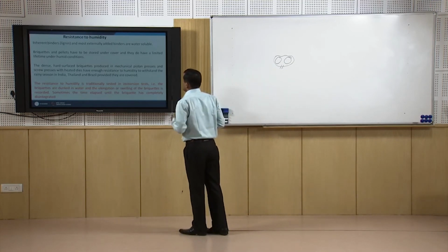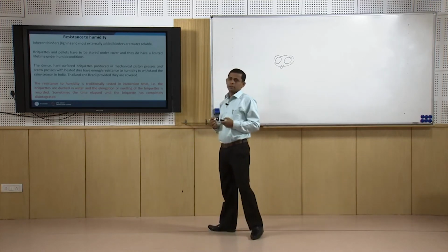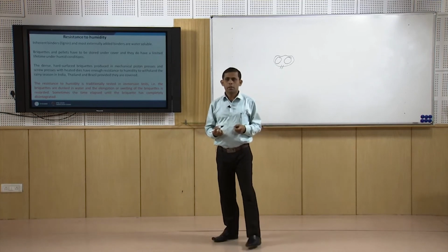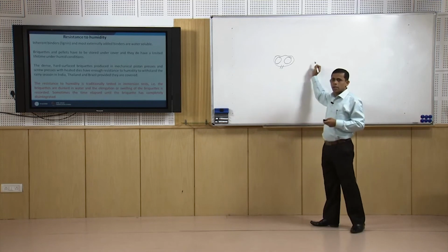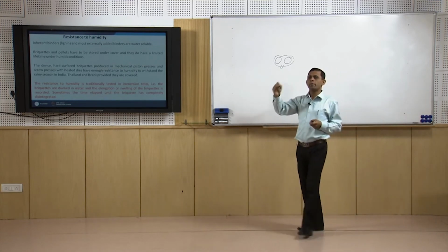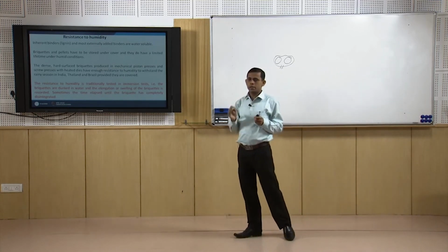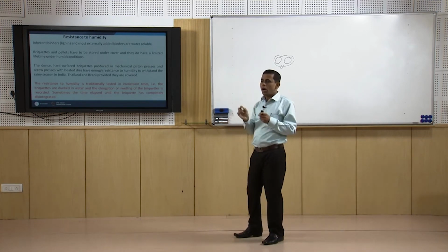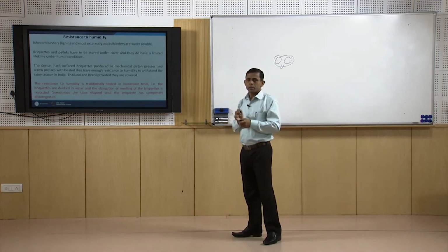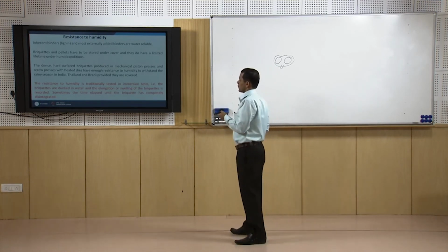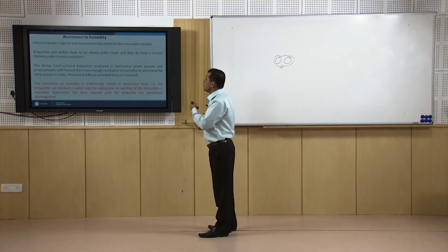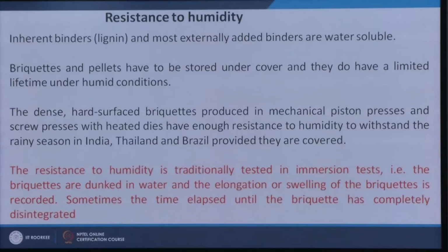So, we have to quantify the resistance to humidity. That means we put the material under humid conditions and see how long it is able to resist, or how it changes its property by expansion. For this, it is traditionally tested in an immersion test. The briquettes are dunked in water and the elongation or swelling of the briquettes is recorded.